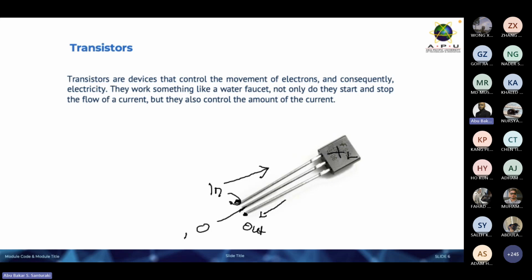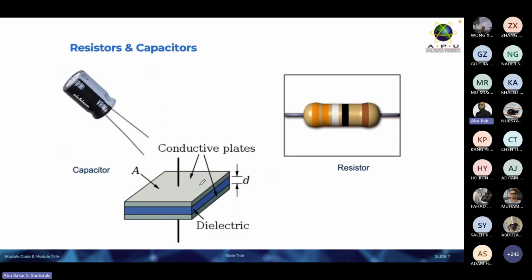So I can attach this transistor to my motor. So the power cable goes into the in, the out goes to the actual motor. And then I have another pin in the middle that I can send the control signal, which is a 0 or a 1 to open or to close the gate. Then I have next here a resistor and a capacitor.